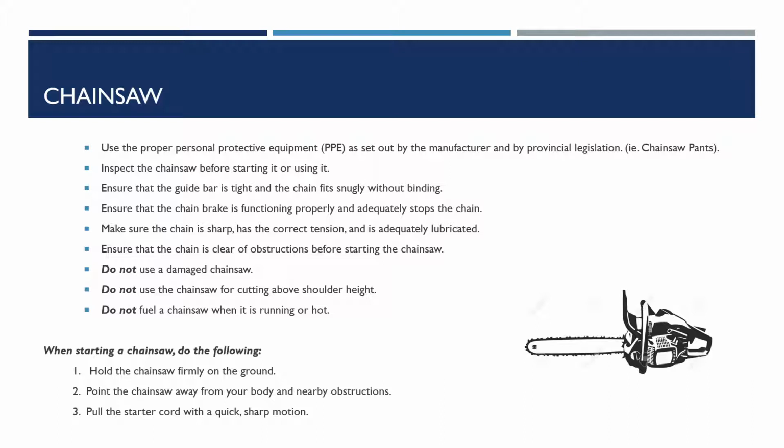Do not use a damaged chainsaw. Do not use the chainsaw for cutting above shoulder height. Do not fuel a chainsaw when it is running or hot. When starting a chainsaw, do the following. Hold the chainsaw firmly on the ground. Point the chainsaw away from your body and nearby obstructions. Pull the starter cord with a quick, sharp motion.